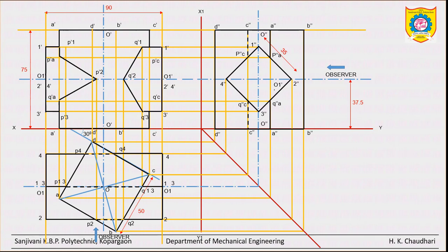Now remaining edges means now up to P2 there is no intersection, so join, and similarly for the right side. Okay, and now in between, that means from this point here to here, this point is not the P1 point, this part P1 is here. Okay, so from here to here we can make it hidden.